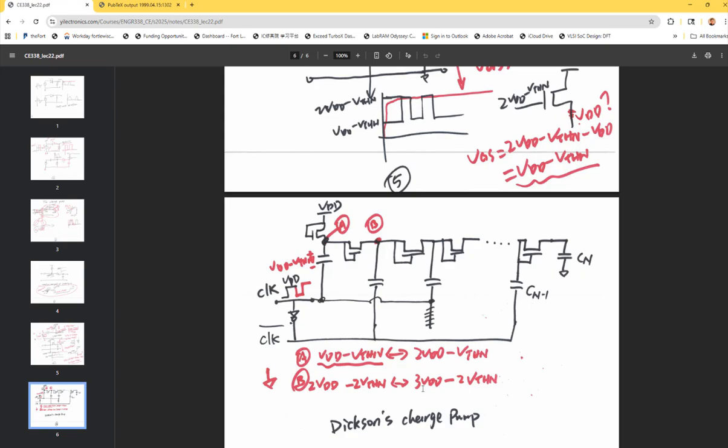Well, because they're like stages. Oh, it stays. Aren't they like stages that go into each other? So that makes sense, and they should do the same thing. Because it's a charge pump, they should be increasing each stage by 1 VDD, but also decreasing them by an extra VTH. That makes sense. It stays, right? Whenever this one got 2 VDD over there, it pushed again, so you got one more VDD added to it. Yeah, that's why. All right, thank you.